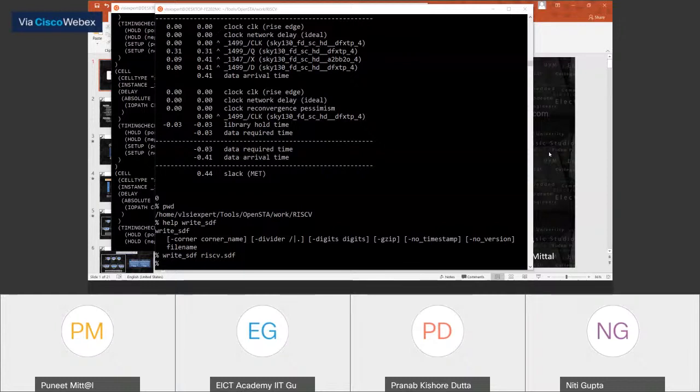Now, Harish, let's try to understand the importance of .lib. In the .lib, there are the cells, the cell names, and each and every cell has its own certain parameters in terms of power, delay, transition, capacitance, and even basic area.